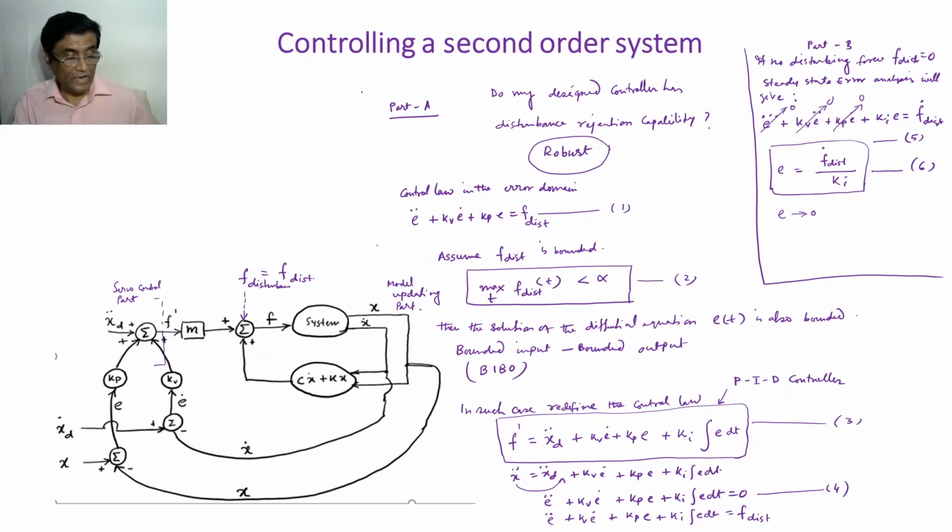So our take home is: in the system, if you have a disturbing force, then you should deploy this kind of control law, which is given by equation number 3. Okay, so that's the reason why the control law has this integral term. Now it is clear to you after taking 2-3 steps. Earlier it was not clear, as if it came from heaven, right? But yes, the reason is, if there is a disturbing force, then our PD control could not handle it, right?